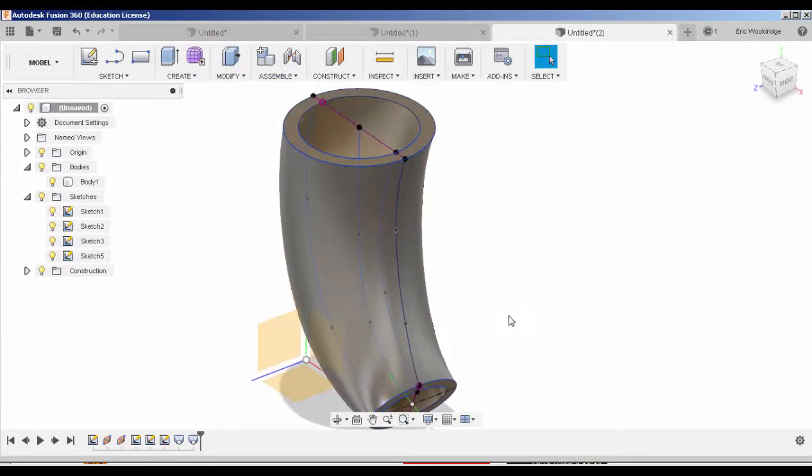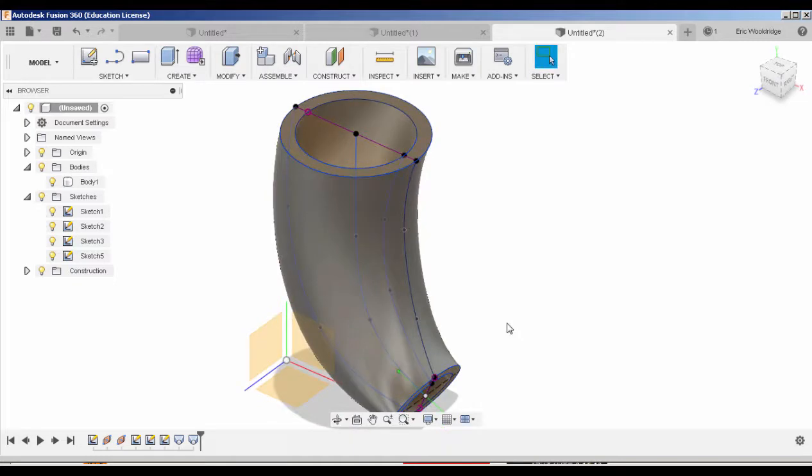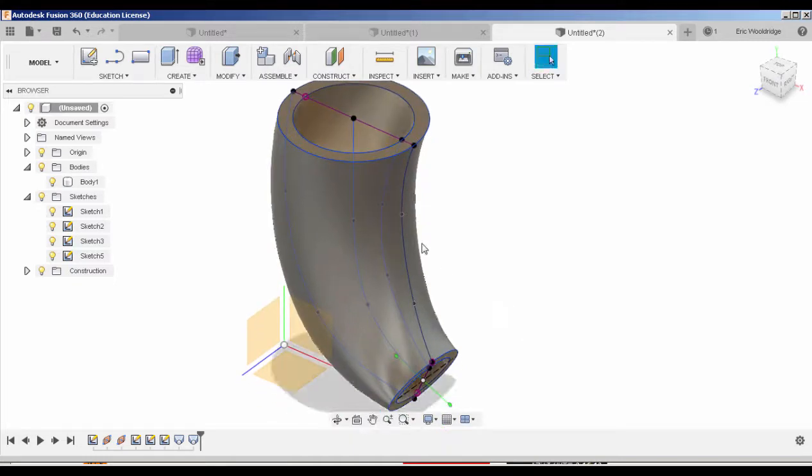So you see what I actually had to do is make a lot of sketching lines. The first one was the one that just helped me create the center, the actual sketch planes. The second one was the one that helped me get the outside profile to work with it. The back one, let me sketch some of these out while I'm talking about them, was the one that helped me create a little bit bigger, more smooth transition. So I used these two to create my first loft.